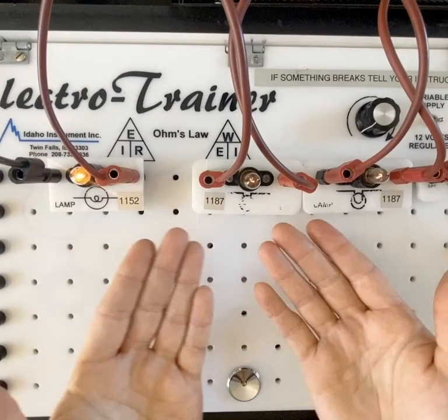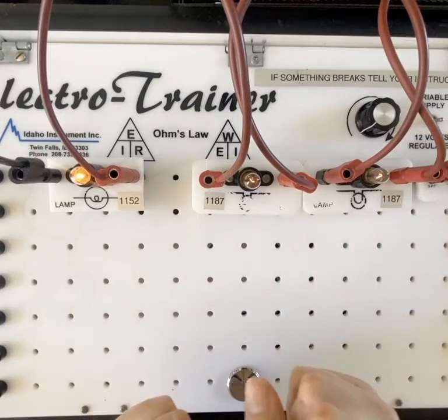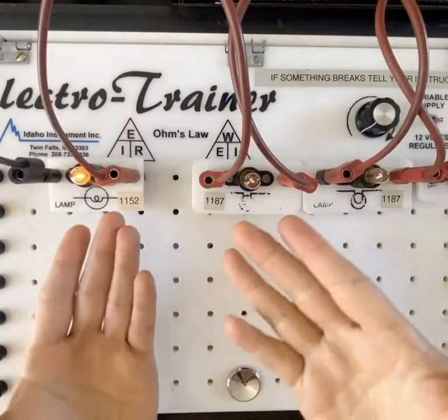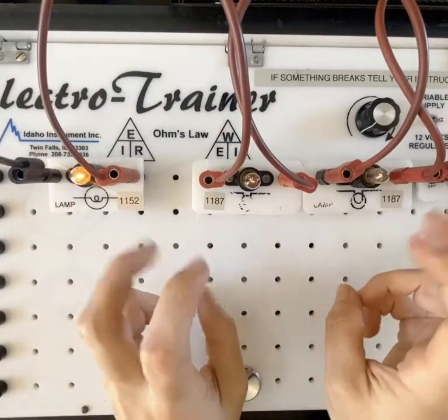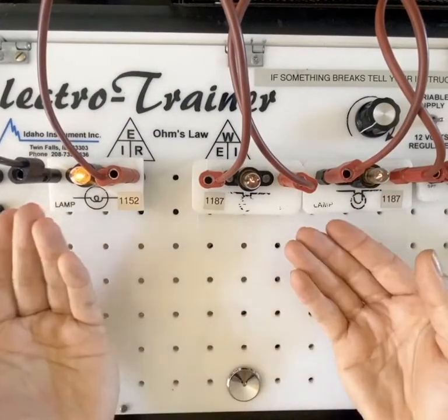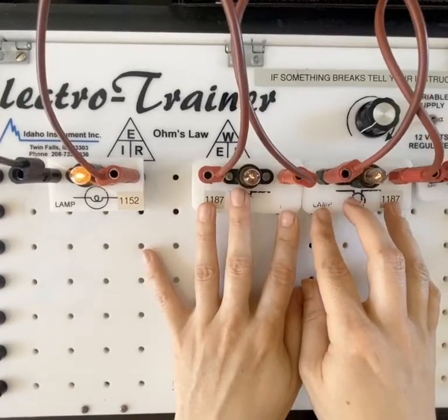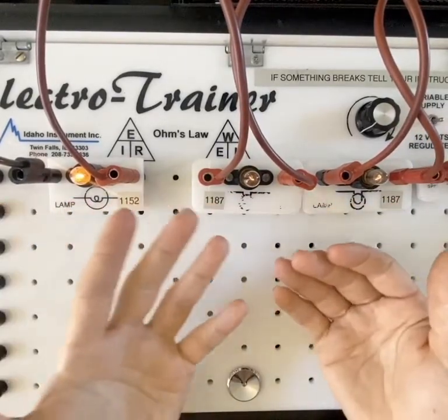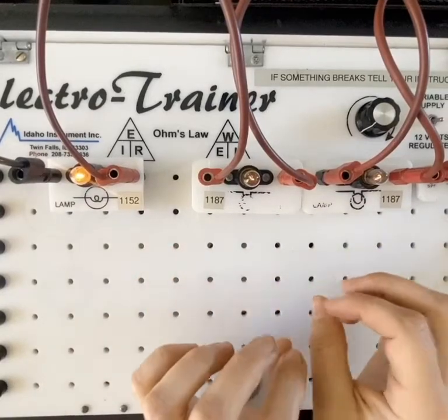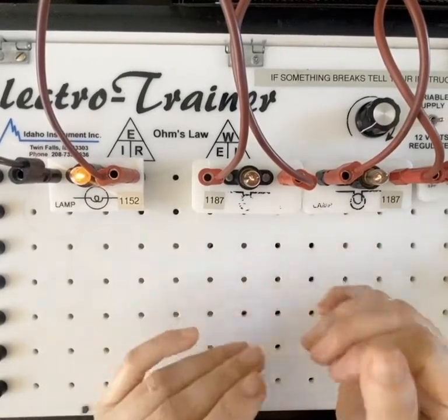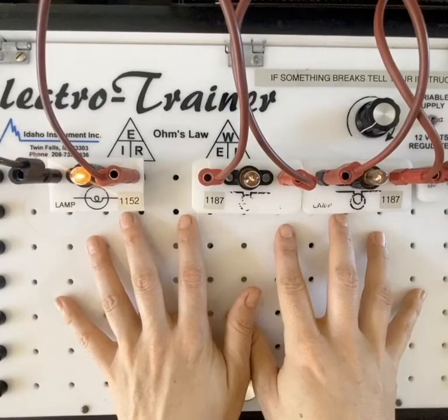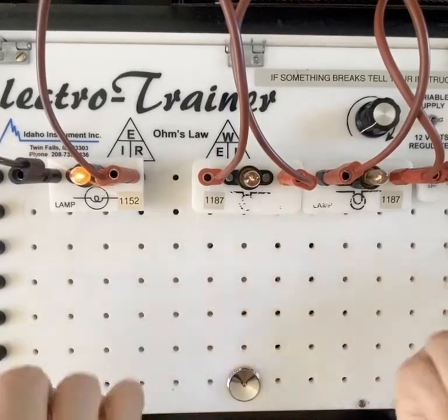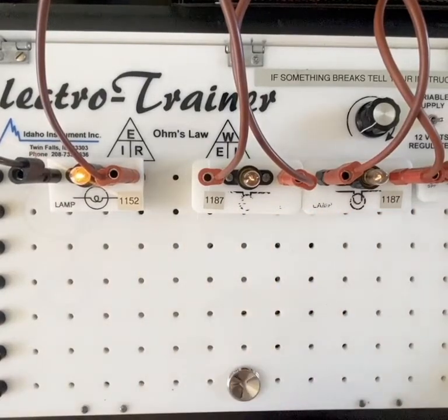They're all getting the same, not necessarily the source voltage, but it's the choo-choo train of voltage going through our loads. Now, since this one is technically at the end of our circuit, wouldn't you think that these would get most of it and then this would get the residual? That's not how electricity works. Electricity will distribute, and depending on the type of circuit, in this case a series circuit, electricity or voltage will get distributed based upon the resistance, no matter where it's at in the circuit.